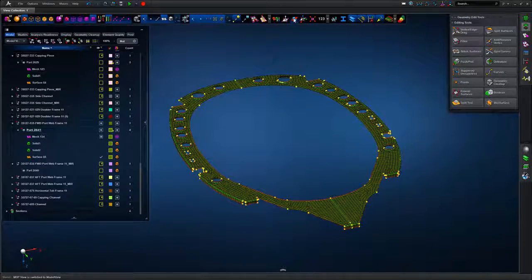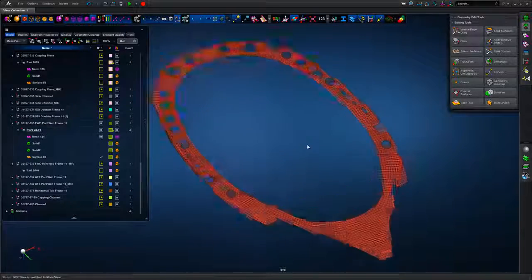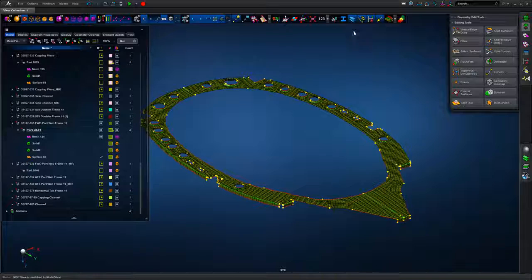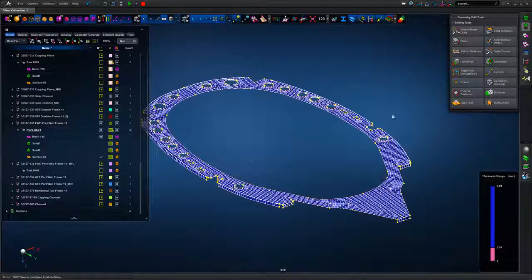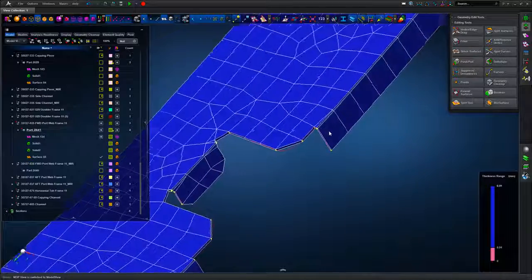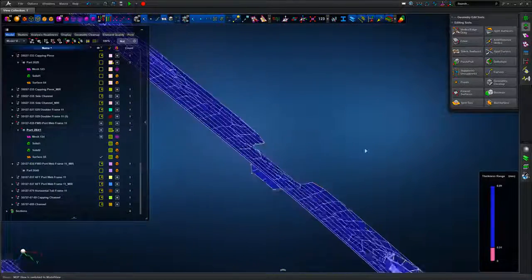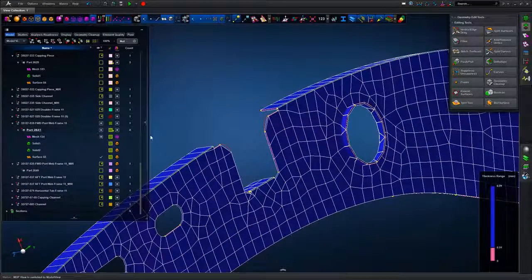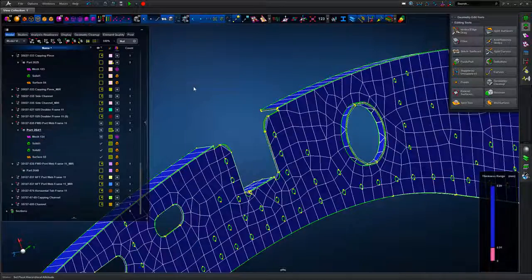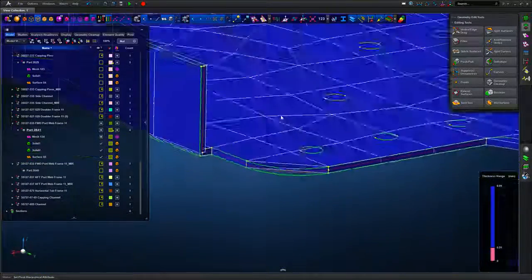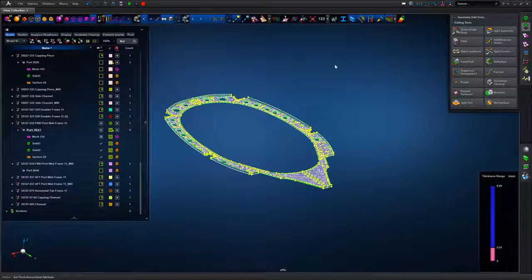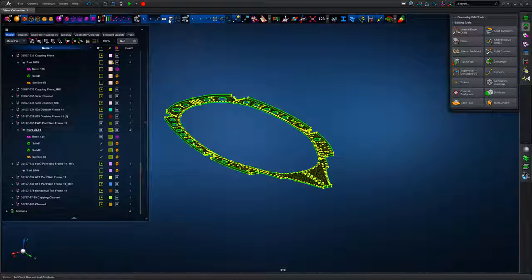loads level fidelity, we're perhaps not so concerned about local detail at this stage. We're just trying to get a meshing on the structure to allow us to understand the overall stiffness of the structure and load path. So checking the element normals and normal consistency, and then looking at the shell thickness. If you remember from the mid-surfacing operation, we had auto thickness turned on, so the shell properties have been populated by that auto thickness parameter, and we can look at the solids overlaid over that resultant shell mesh definition. We see we've got a perfect definition in terms of the shell property to 3D CAD thickness.